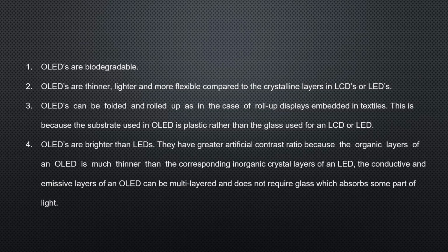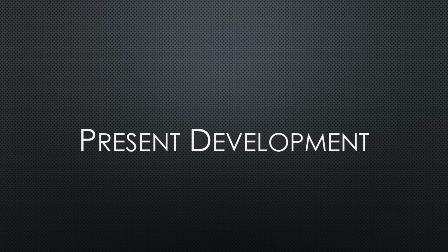OLEDs are brighter than LEDs. They have greater artificial contrast ratio because the organic layer of the OLED is much thinner than the corresponding inorganic crystal layer of an LED. The conductive and the emissive layer of an OLED can be multi-layered and does not require glass, which absorbs some part of the light. Now let's have a look over the present development with OLEDs.